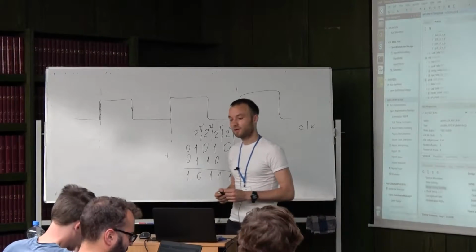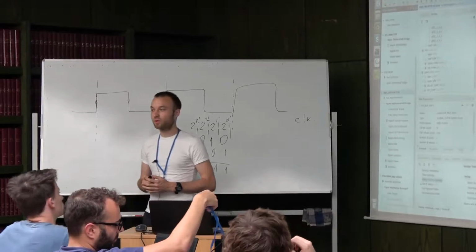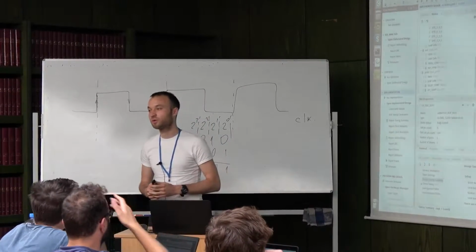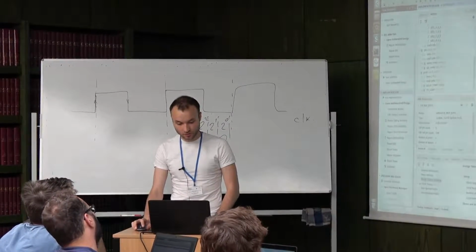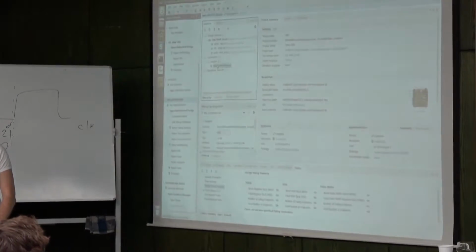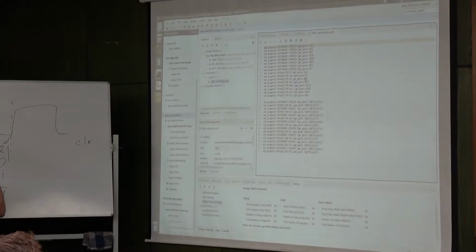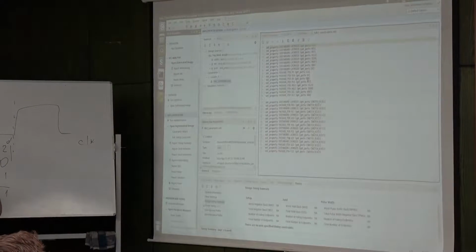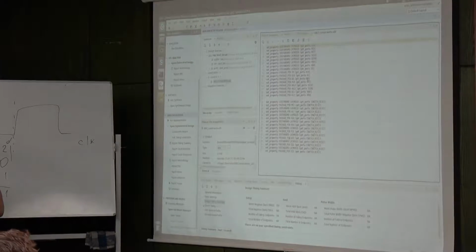For the third lab, I would like to cover the most common questions that were coming from the second one. And most of the questions were related to constraint files. So in addition to the VHDL code that we add in the source pane, we also supply Vivado with this constraints file. These constraints are additional directives that tell Vivado that we want to satisfy certain timing, routing, or other constraints. In this case, we have only used routing constraints.